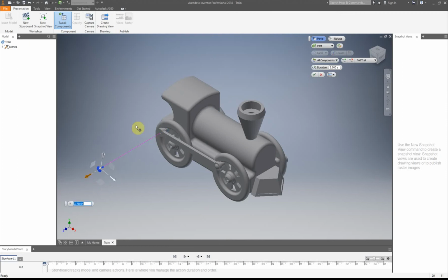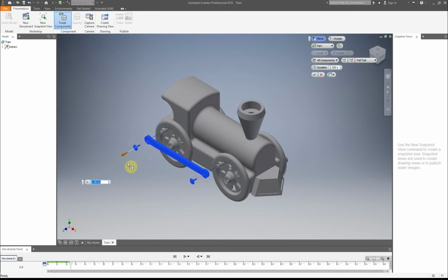All right. So I'm actually going to undo that. So I'm going to click on cancel there to show you something that's neat. So you can click on the first item that you want to move, press shift on your keyboard and hold, click on the next item. Then we can move these two. Now I want to add in the linkage arm to this, so I press and hold shift again, click, let go of shift, click on the arrow, move it away a little bit more.